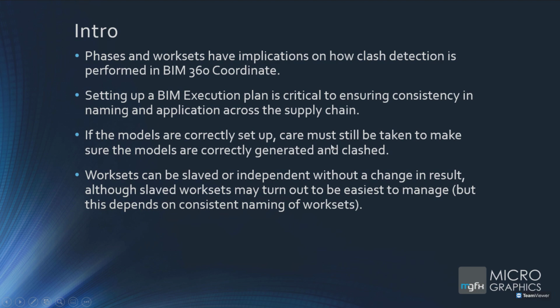If the models are correctly set up, then you must be very careful to make sure that the models are correctly generated and clashed. Worksets can be slaved or independent without a change in the result, although slaved worksets may turn out to be easiest to manage. This depends on consistent managing of worksets. So it sounds like a mouthful, but it's actually quite easy to understand, and we'll illustrate that shortly. So if this is Greek to somebody here, don't be concerned about that now. You'll see it in action shortly. And then if this is old news to you, then please bear with us